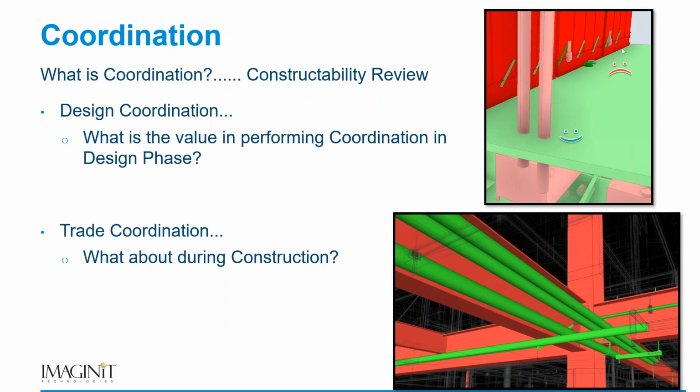But if you think about it logically, in this first image we see potentially these are risers that come up to, say, some rooftop equipment. Eventually down the road, you're going to have to place some sleeves in there, but ultimately that's a legitimate penetration, an interface from pipes to concrete, for instance. That's totally legitimate. We're good to go there. We understand it. We've identified it. We can move along. We don't have to create an issue.